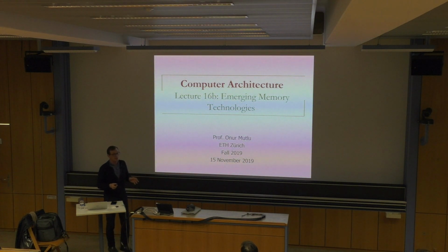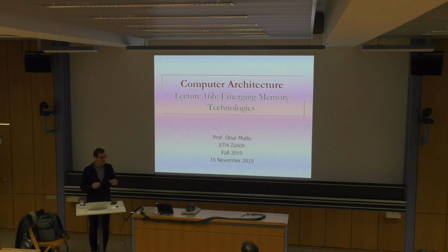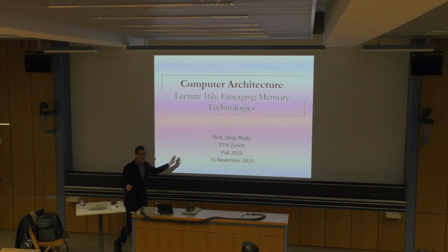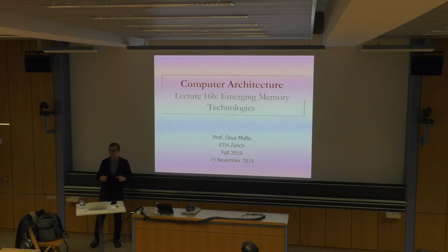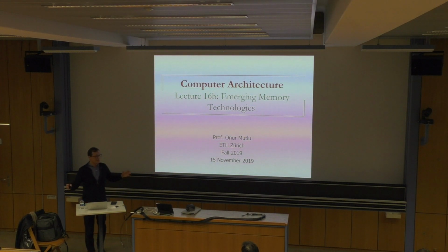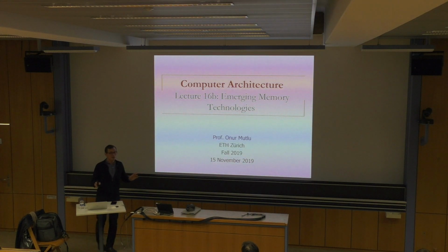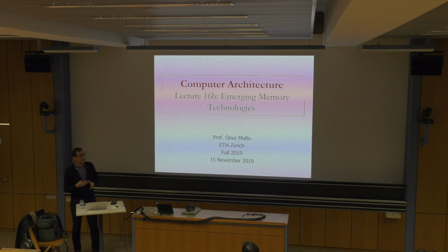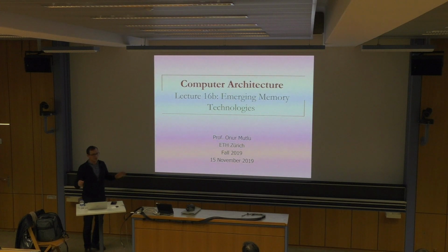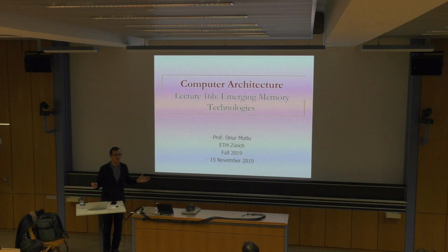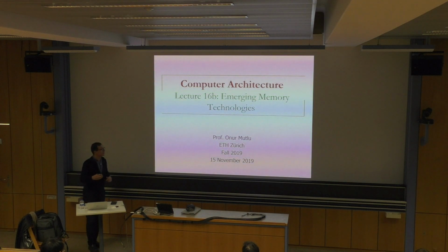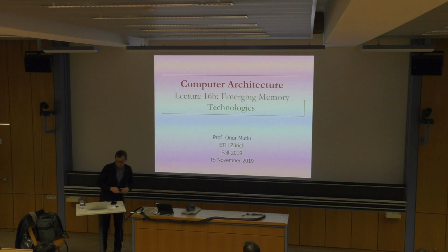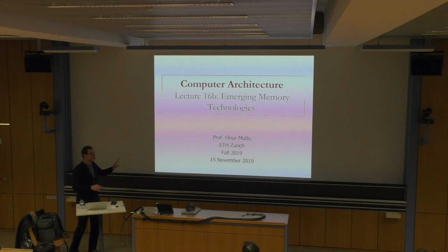What I'm saying is some of these technologies have the potential to replace SRAM, the large SRAM memories that we have on chip today. For example, STT-MRAM is a very good candidate for potentially replacing L2 and L3 caches, because its density is similar to SRAM, and it has characteristics that are also similar to SRAM. But it also has the ability to keep the data. I don't want to say forever, but it's essentially non-volatile, whereas SRAM is volatile. So it can provide on-chip non-volatile storage if it replaces part or all of your SRAM. So the focus here is on high performance.